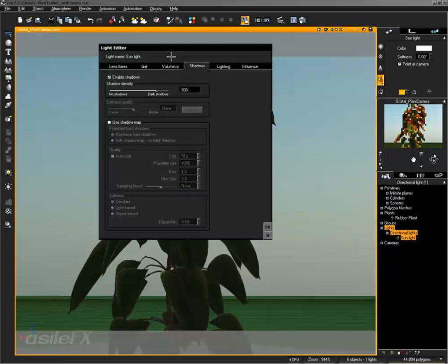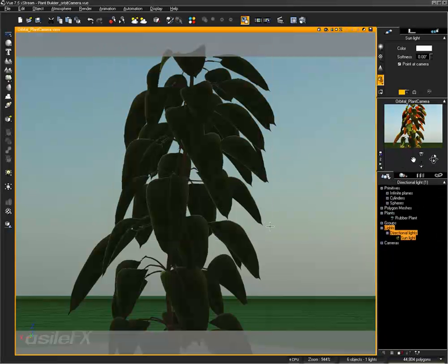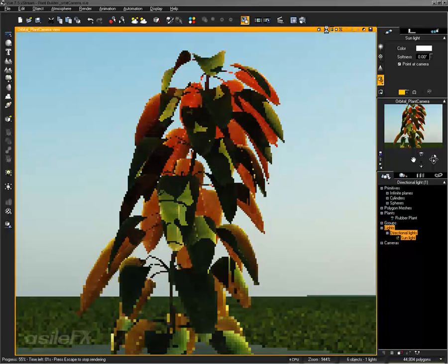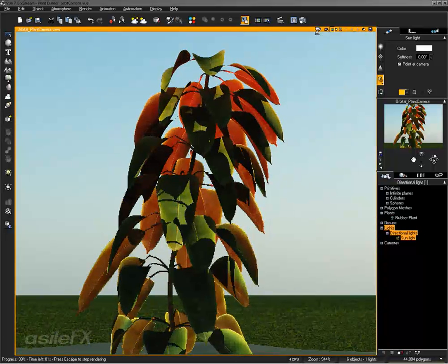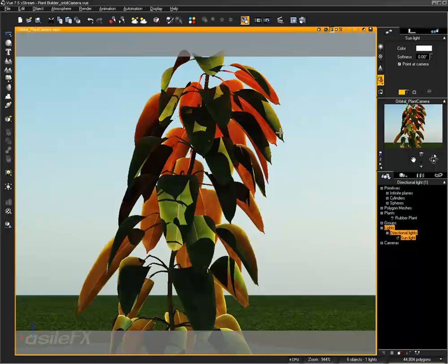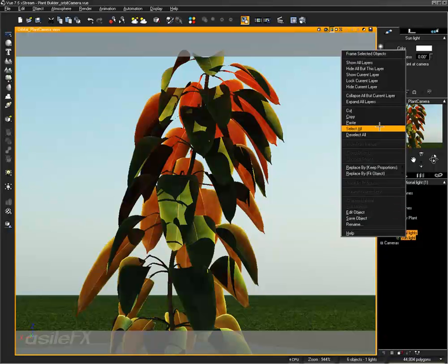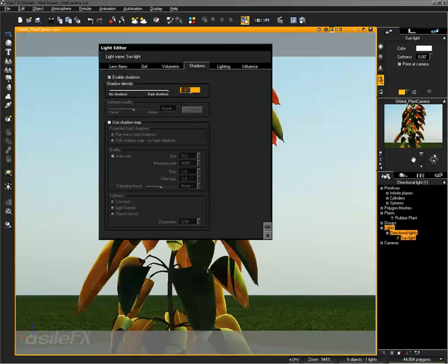Now this is connected to the sunlight shadow. If I turn up and increase my shadow amount, I had it set to 80. So let's go ahead and increase it to 100. You're going to see a decreased effect where the shadows are hitting the leaves, which is pretty much going to be everywhere always. And if this is too dark, which it pretty much always is, because that default value of 100 is just way too high. You should almost never use the value of 100. Anywhere between 70 and 80 usually works pretty good.